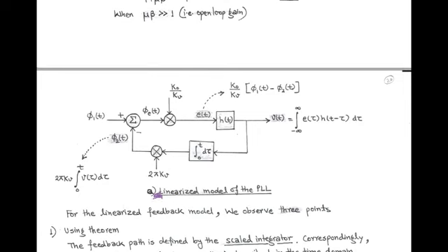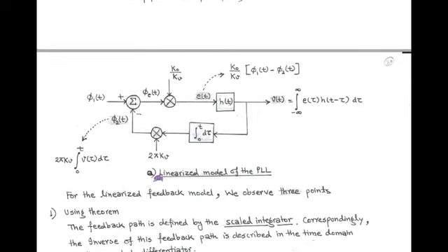Now, we are going to apply this theory on our PLL model. For this, we represent the linearized feedback equation using a block diagram, as shown in the figure. There is a negative feedback because we know that the error angle phi_e is given by phi_1 minus phi_2, where phi_1 is the angle of the incoming FM wave and phi_2 is the angle of the locally generated FM wave in the voltage controlled oscillator. So there is a negative sign with phi_2 and we have a negative feedback system.